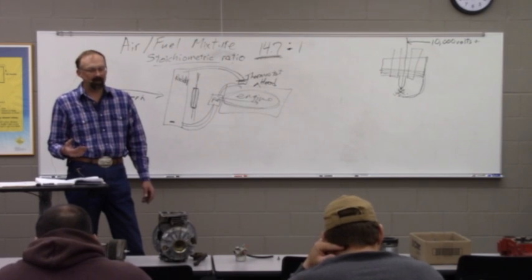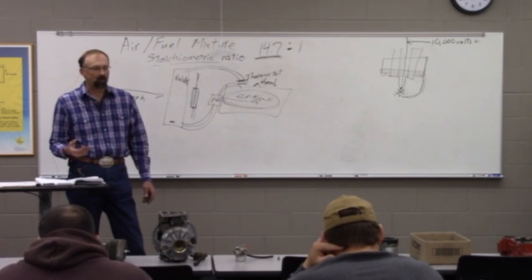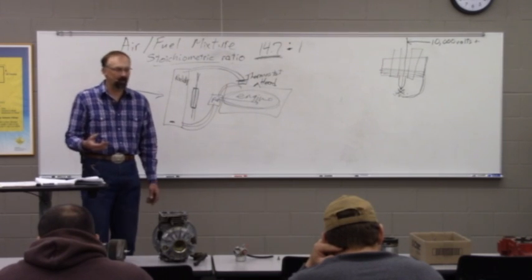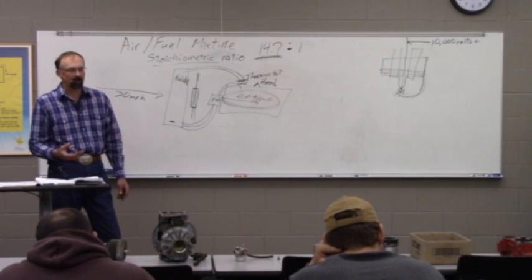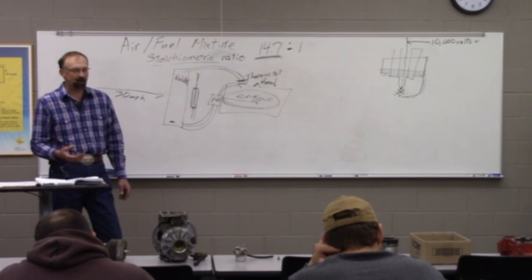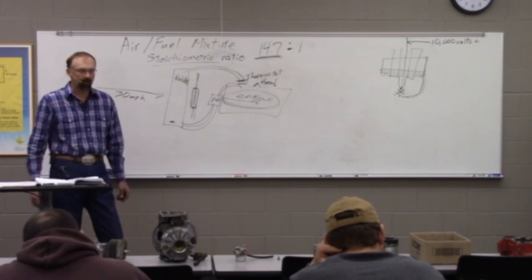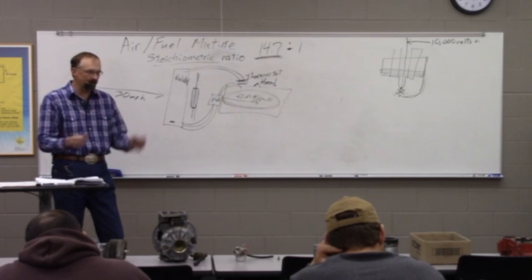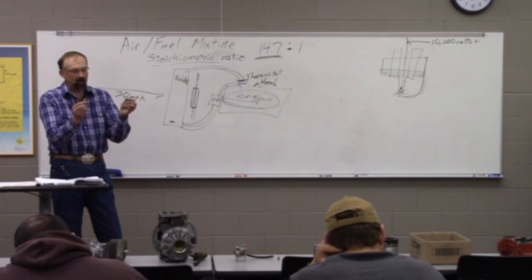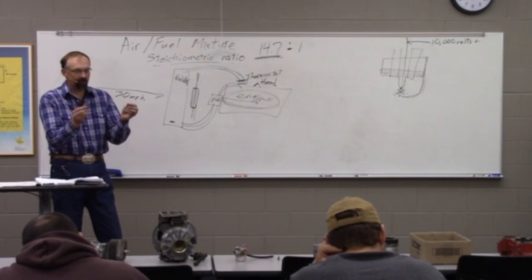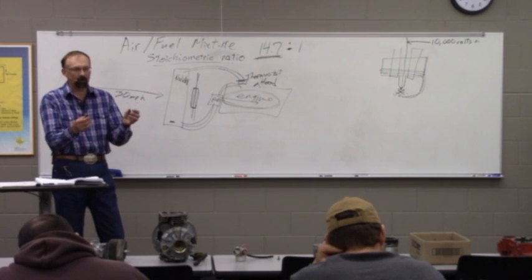Where we see a big difference is in the gear oils. We'll typically with natural oils, by the time you get 50,000 miles on a rear end, that oil's pretty well trashed in that gearbox. You rub it between your fingers, and you rub new oil between your fingers, and you can feel a dramatic difference. With the synthetics, boy, a lot of times we can see it go twice that long. Some of it depends on how hard the truck is pulled and that kind of thing.